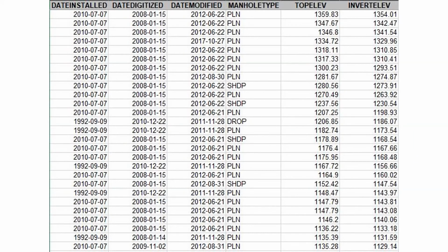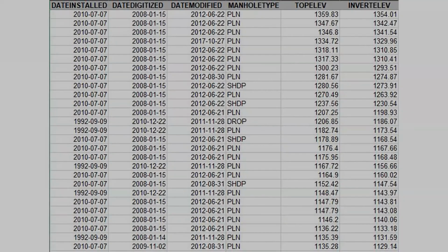And we were able to use a definitional query and the manhole information to select pipe or manholes that were in the appropriate depth range, and then look at the pipe that is connected to those, and basically back our way into figuring out which pipe was in that critical depth of bury that they were focusing on. And we were able to use that to make a map like this.